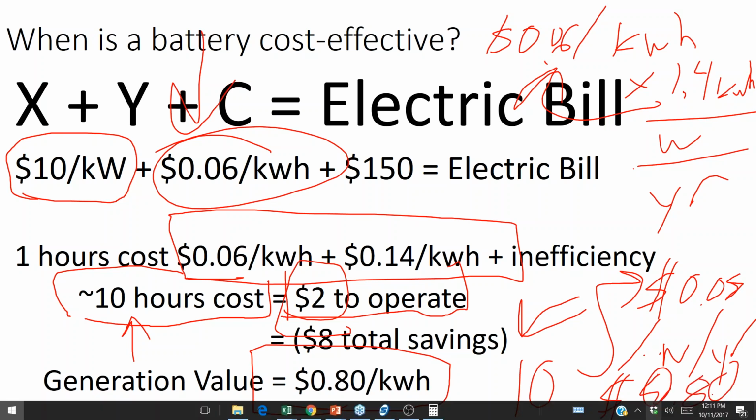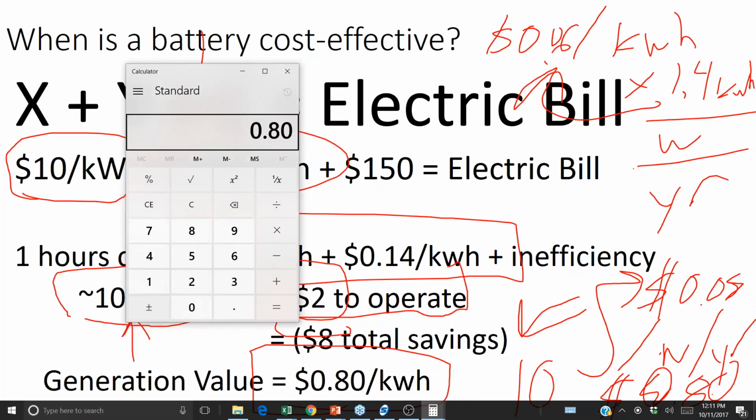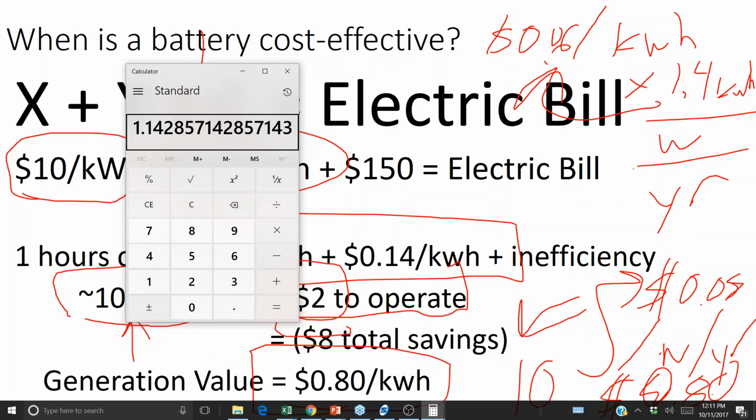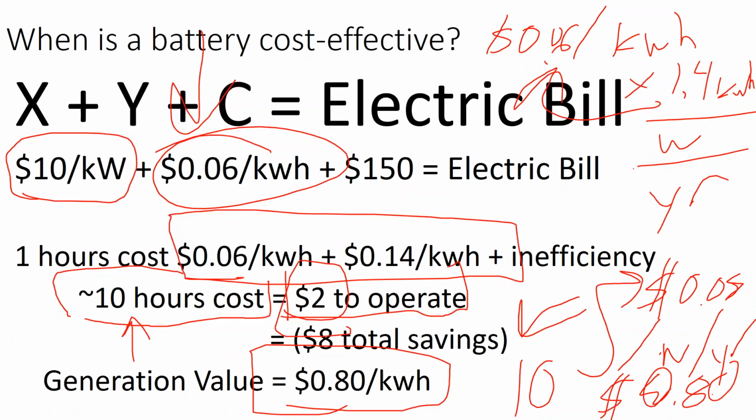And then if we back out the federal tax credit with that, 80 cents a watt divided by 0.7, we really need a commercial array install rate of around $1.10 to $1.15 a watt for that commercial array to even begin to make sense. And most commercial customers, they don't want a 10-year payback. They want something less than a 10-year payback. So commercial flat roof markets where the price of electricity may be 12 cents, because the solar array can only generate at 6 cents, the economics are not there. And that's why we don't see all these flat rooftops with solar.